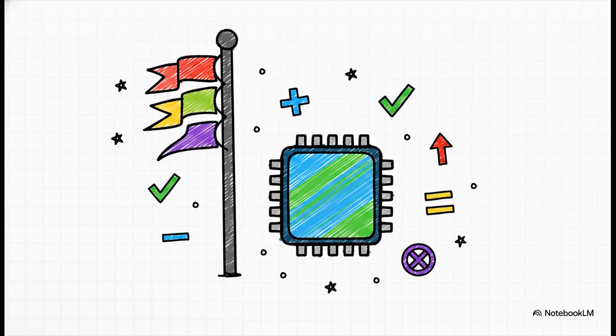The key is that it holds specific flags. So while your general purpose registers are busy holding the actual numbers, the status register is holding single-bit flags, things like carry, 0, negative, and overflow. These little flags tell the CPU the result of the very last mathematical operation it did. Pro tip, if you want to seriously impress your examiner, mention a real-world example like the current program status register or CPSR in ARM architecture.